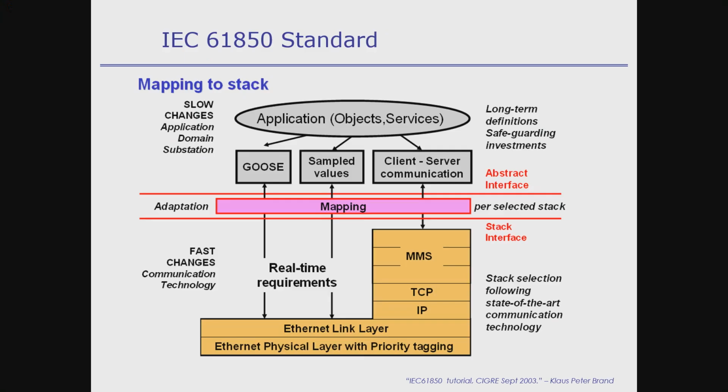The other service is sampled values. Remember the process bus, the data is sampled. All the voltage currents are sampled, and sampled values are sent over the process bus, and any IED can access it, right? So obviously samples are happening every, let's say 1 millisecond, 1 by 1,000 seconds, right? For example, but nowadays it's even more. But they are coming regularly, right? So data is getting thrown on the process bus. So obviously, in order to transfer that, it's very time critical.